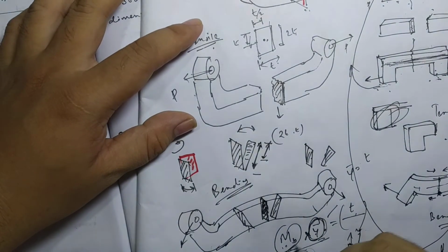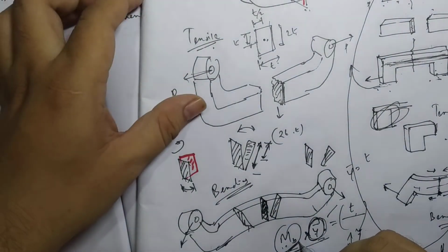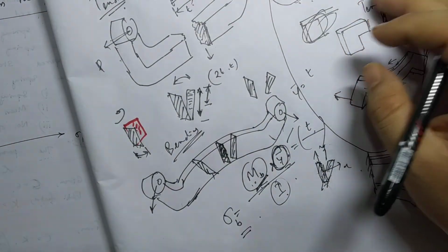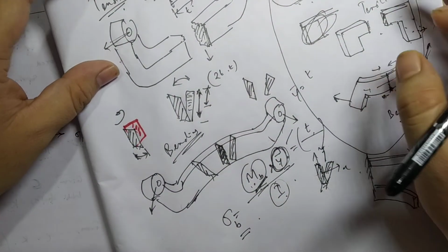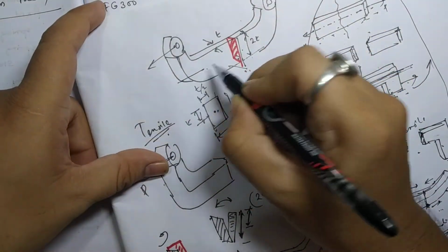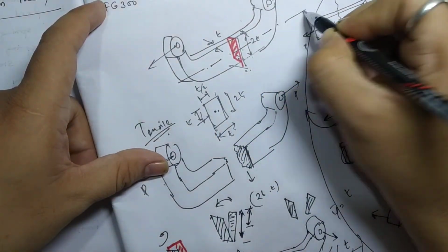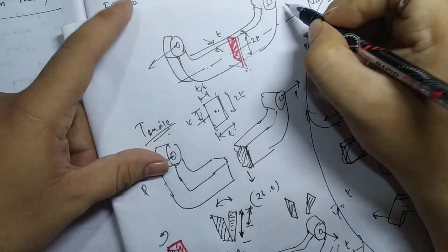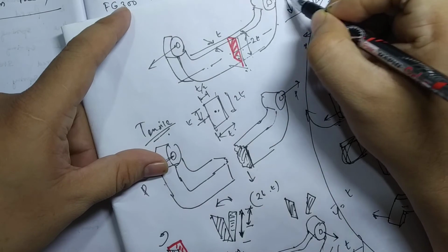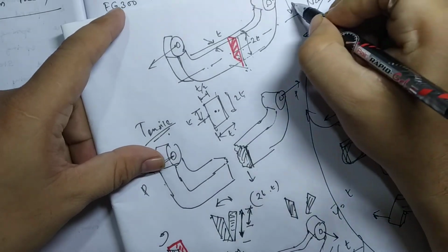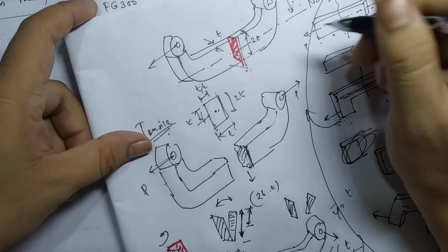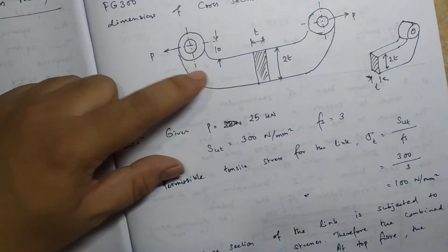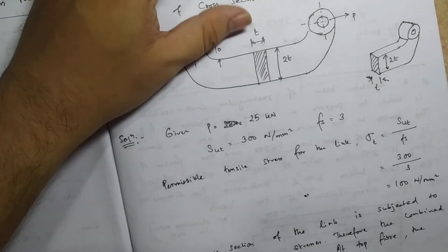Okay, bending moment you have to find out. What is the bending moment? That is force into perpendicular distance only. So up to which perpendicular distance we have to find force, and here this is the axis, or this is called neutral axis. Here there is no stress, so from point of application of force up to the distance of neutral axis is your bending moment here. So that distance is given to you. Okay, so 10.